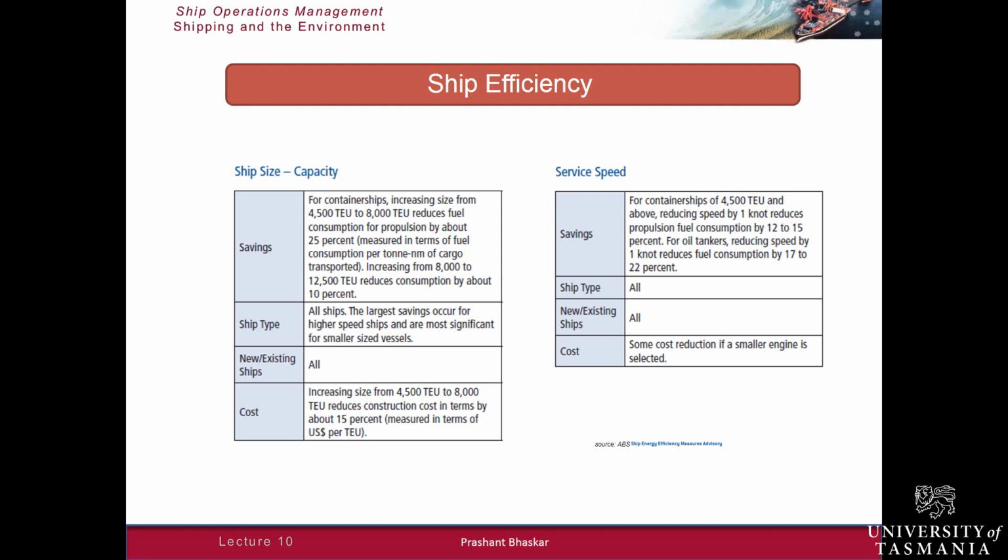Having said that, I think we need to be cautious here. These efficiencies are only achieved if the ship is full. So, if you've got a very large ship which has got a lot of TEU capacity, but it's carrying only a small amount of cargo, then that efficiency is not realized because it's operating a bigger engine.